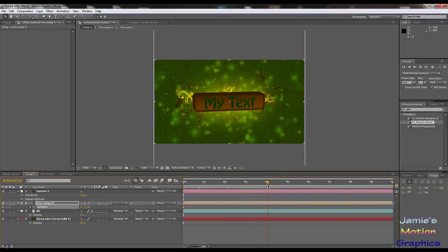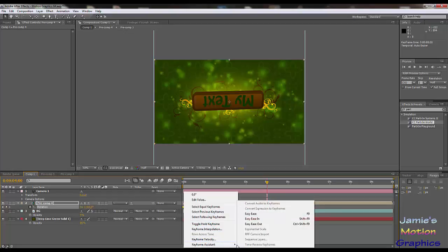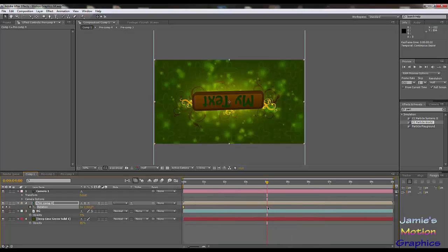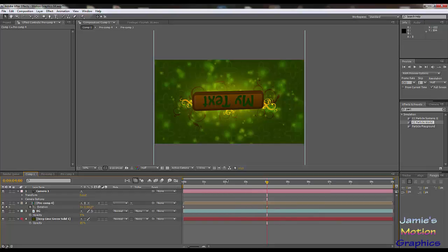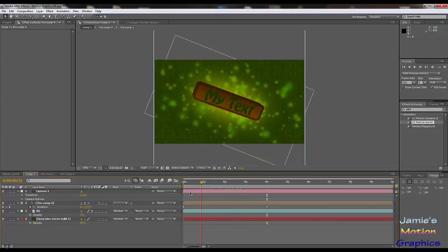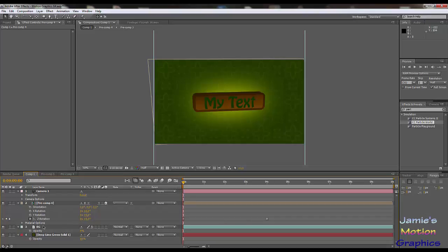You can of course make it quicker or slower by using some time remapping. And we're going to make it a 180-degree turn. You can select both of them, and use easy ease. I can't use F9 on this because it will stop the recording, but you can use F9. So yeah, this is the wrong rotation. That was pretty terrible. Okay, let's do that again, but done with Y rotation.